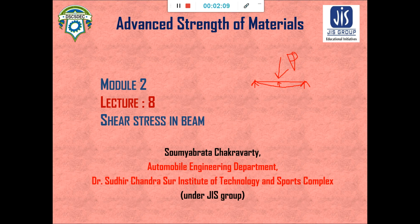When it is shear stress, that is known from our shear force and bending moment diagram. In a beam we can draw the shear force and bending moment diagram like this. This is your shear force diagram, and the bending moment diagram looks like this. Here will be the maximum bending moment. In this type of case, at the point of maximum bending moment the shear force is 0.